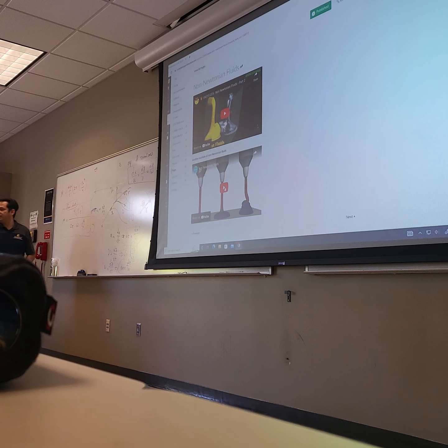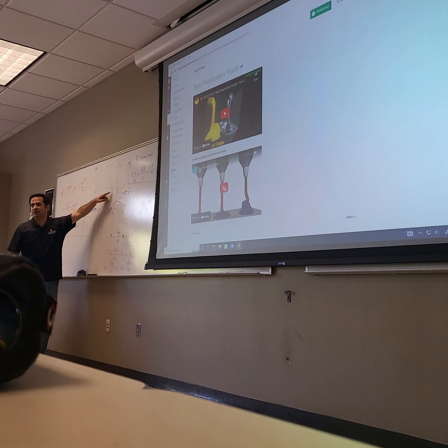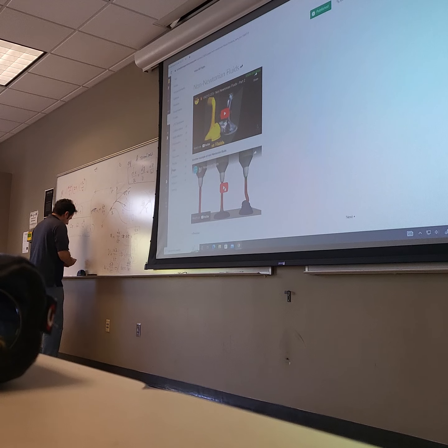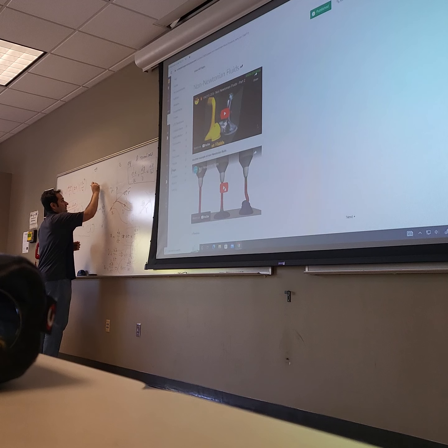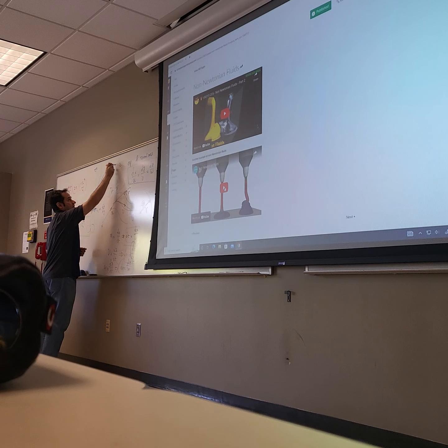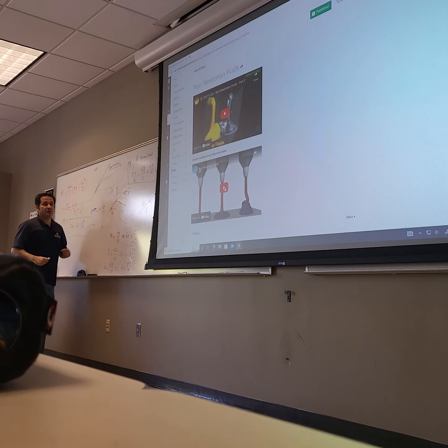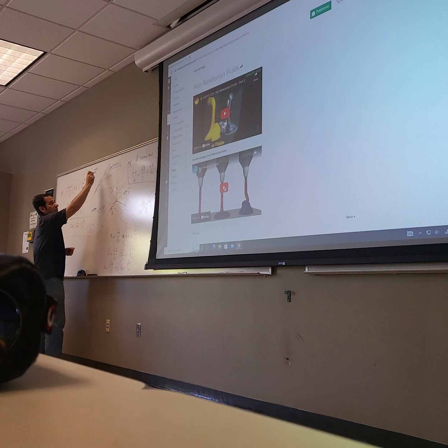This is Newtonian. But if you go to a lab and use different fluids like honey or ketchup, you don't get that line. If you put another fluid in that device that you created, the cylinder, and try to compute the shear stress versus velocity, you get things like this. You get a curve like this. You get a curve like that. Obviously, these curves are sub-Newtonian. This is Newtonian. These are sub-Newtonian. These are super Newtonian.